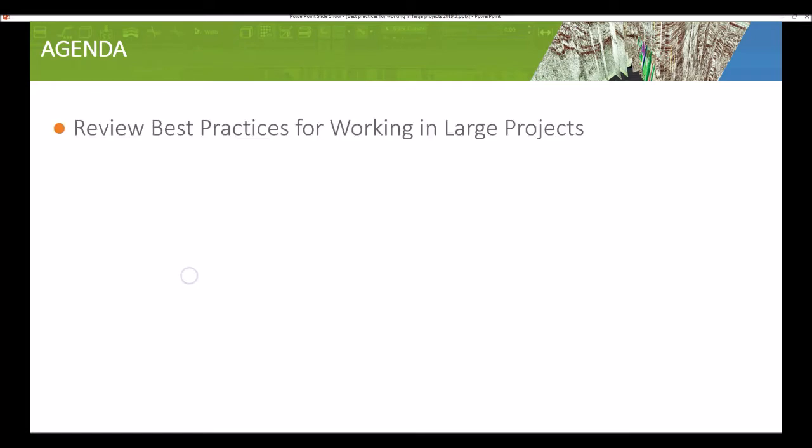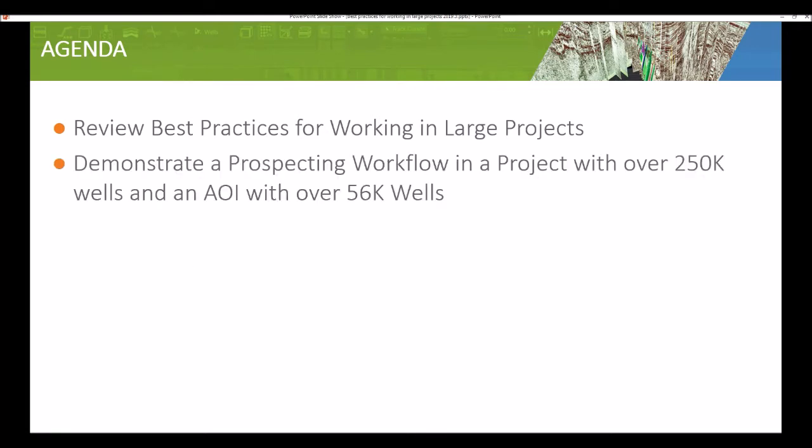And welcome to our webinar on best practices for working in large projects in GVERSE Geomodeling. So many of our projects contain many hundreds of thousands of wells, which is more than you would want to model in any geomodeling application. But by using the following suggestions and techniques, you can productively work in these large projects with good performance and results. Following this review, I will demonstrate a workflow for modeling in a project with over 250,000 wells and in an AOI with over 56,000 wells.